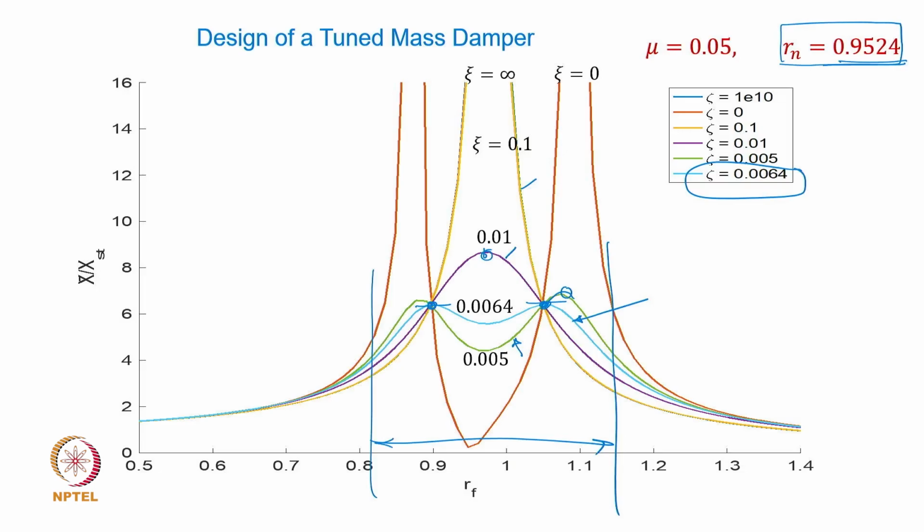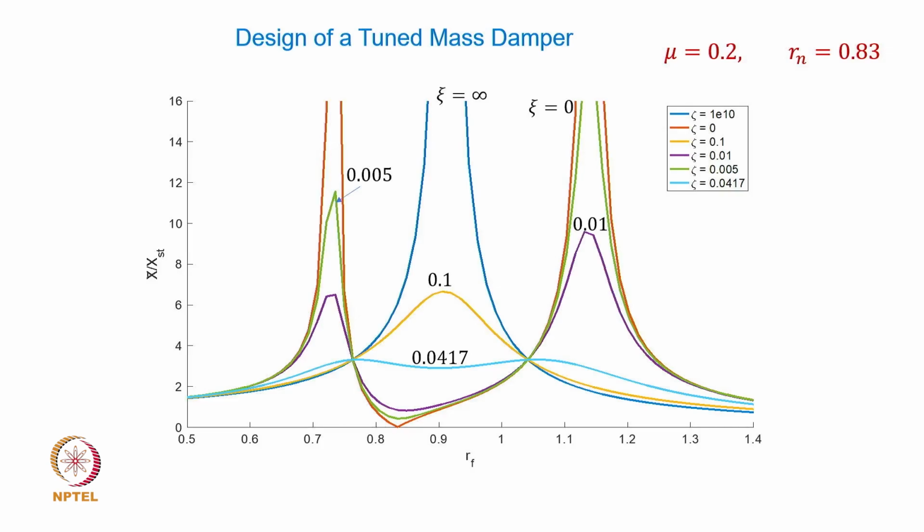Okay, so that is basically the philosophy of design of a tuned mass damper, and such dampers are obviously used in practice in the automotive industry and in civil structures. We have seen them, and our job now is to really look at how to find these optimal parameters.